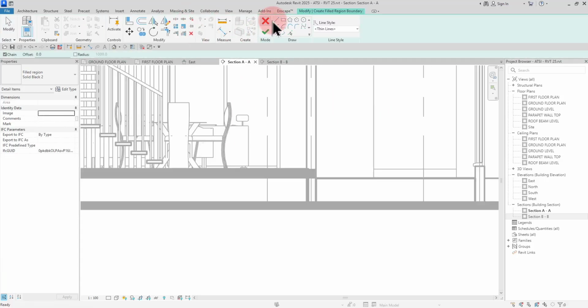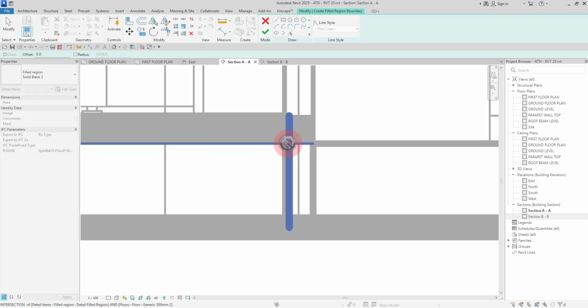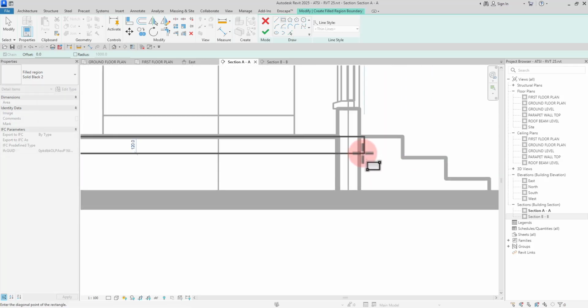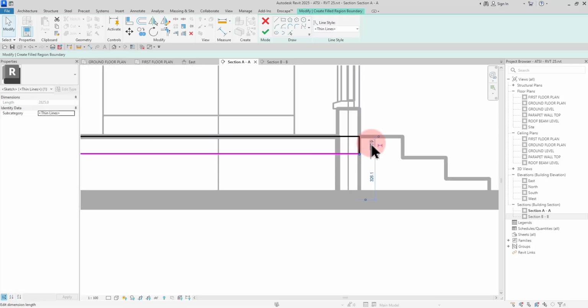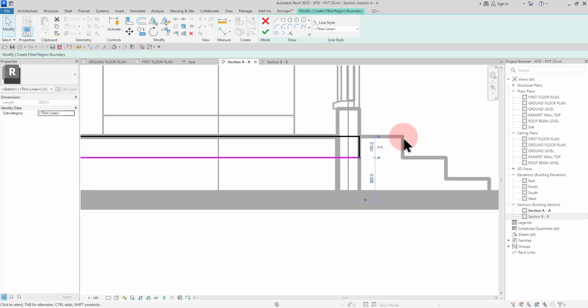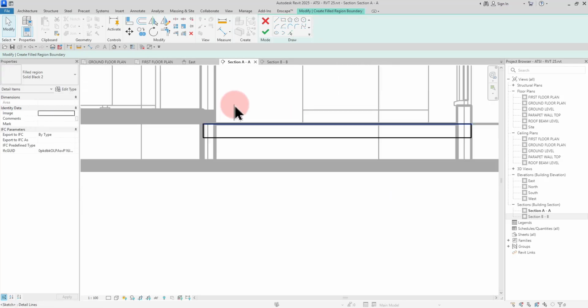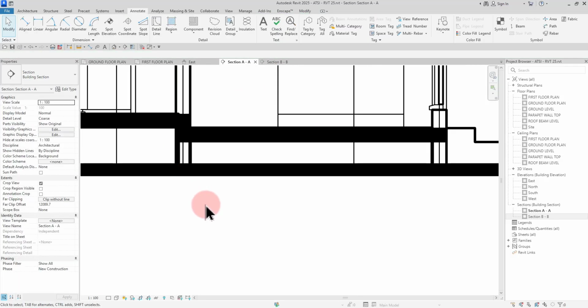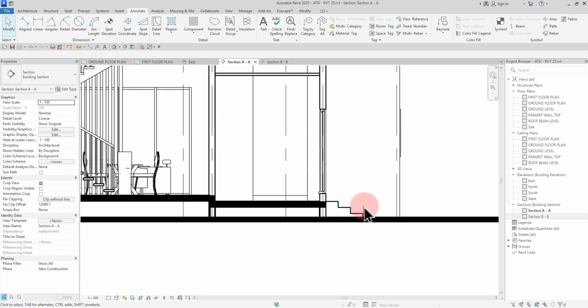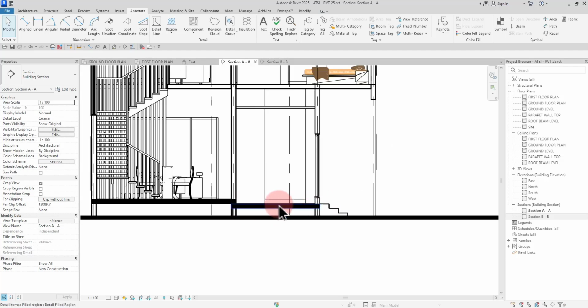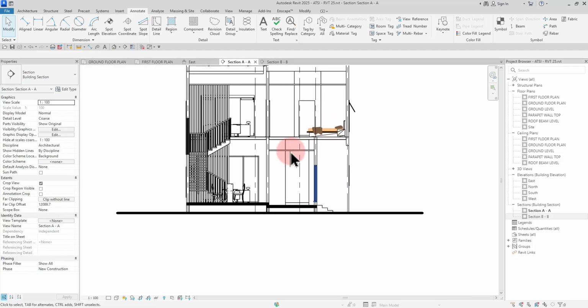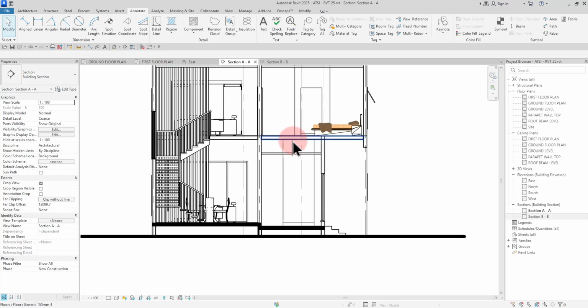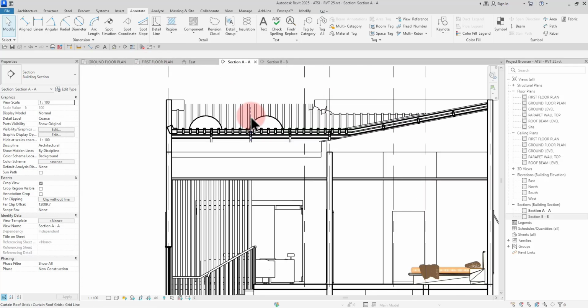So the same thing, head back into the region tab and just bring this also here. Make sure it's 150. All right, the floor slab thickness is 150. Make sure it's 150 when you are placing it in there. You can move this here a little bit. So we have that representing that. So we have a step down over here, 450 in here. So we are going to represent all those spot elevations also in our sections.